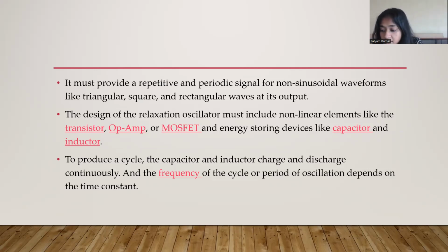So, if there is a capacitor which stores the energy supplied by the external source and releases that energy in another phase, then at the time of charging of the capacitor, the bulb connected to the circuit does not get illuminated. But at the time of discharging of the capacitor, the bulb starts flashing for a time period determined by the RC time constant. This operating principle is adopted by the relaxation oscillator.